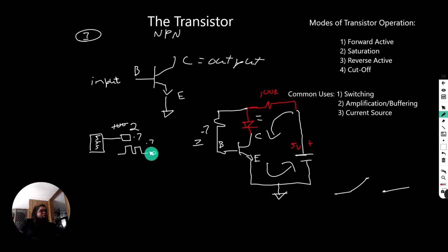Okay. Now you could take this circuit, and if you have a breadboard, you can figure out what bias voltage you might need to bias the base, and you put a resistor there to bias the base, and you have a completed circuit that will work. And we'll do this on the breadboard as well. We can do that in a demonstration video. But again, this is a large topic, so we're going to do it in small pieces, small bites.